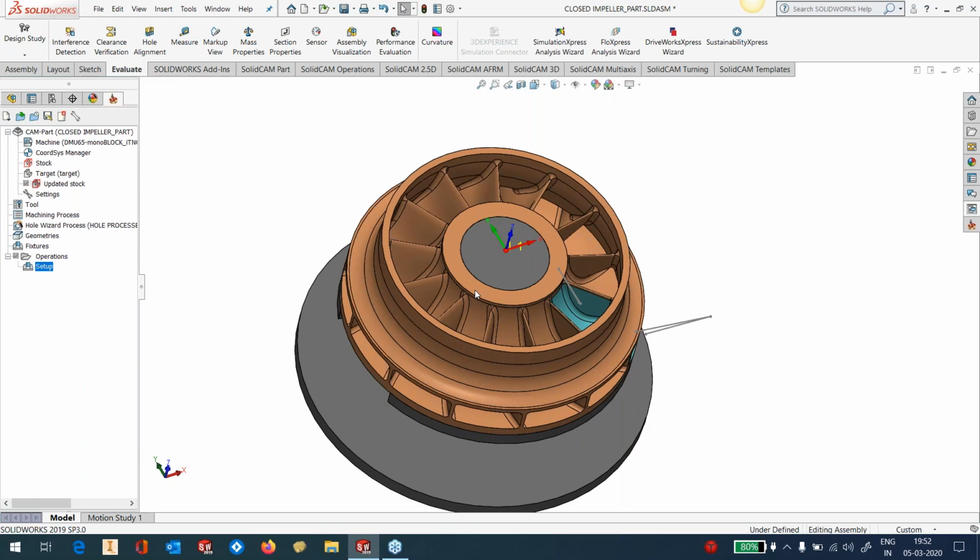Okay. Now you will ask me, what do we do with the roughing? Well, roughing can be done in 3+2. After the end of the webinar, when I will send you the files like I did last time, the files will include all the roughings that were done in different positions. I do not want to touch the 3-axis part again because it's simple 3+2 operations. But in the final file, you will have all the operations of 3+2 also included. What we are going to do today is we're going to see the 5-axis part of the operations.